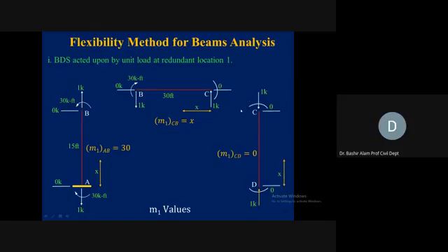Now joint C, we need to put in equilibrium. One kip to the right of joint C is in the downward direction, and to the left it is in the upward direction. So in the vertical direction it is in equilibrium. Horizontal here is 0, so here also it is 0. Moment is 0, so 0 moment is transferred.